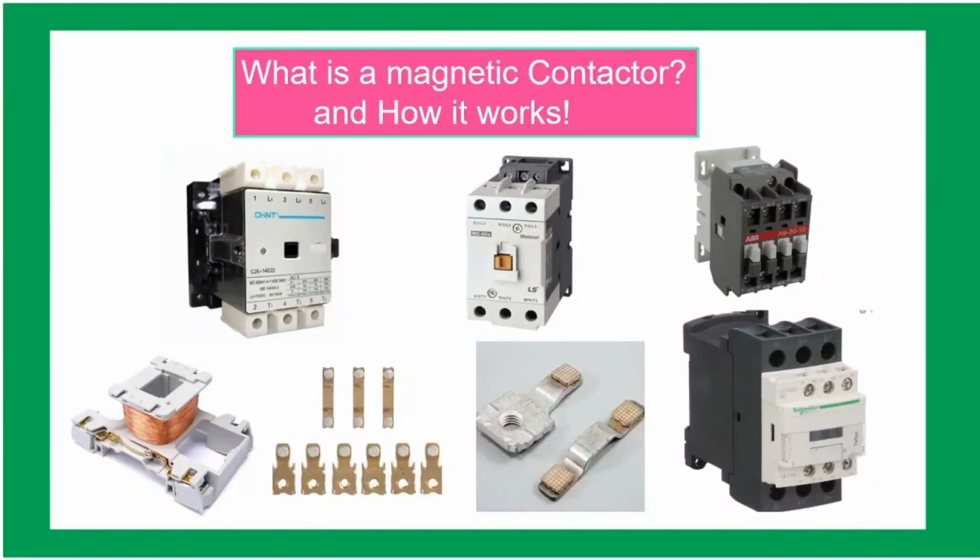Hello everyone. Today we're going to discuss what a magnetic contactor is and how it works. A contactor is an electrically controlled switch used for switching a power circuit, similar to a relay, except with a high rating, as high as 5,000 amperes. A contactor is controlled by a circuit with a much lower current and voltage, like 24 volts DC, and is used in applications ranging from light switches to the most complex automated industrial equipment. It is used by electrical equipment that is constantly on or off, opening and closing a circuit.